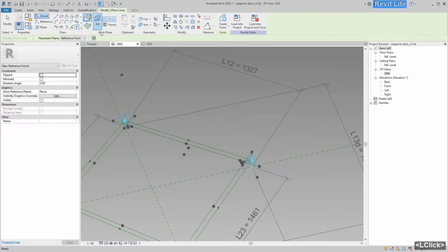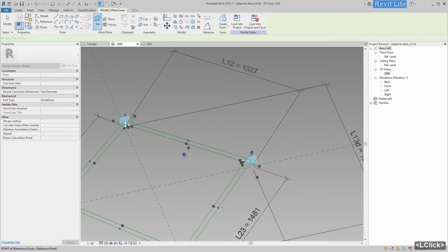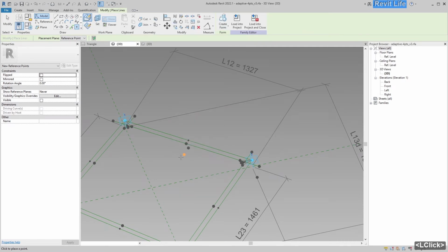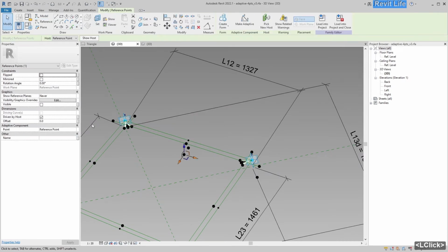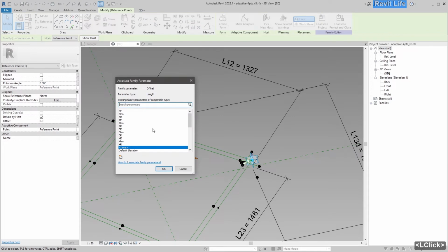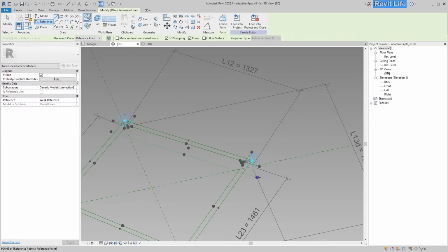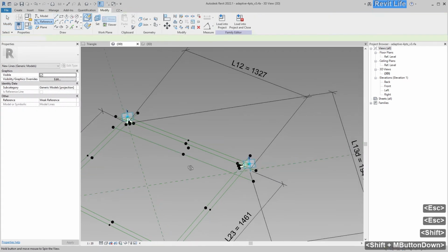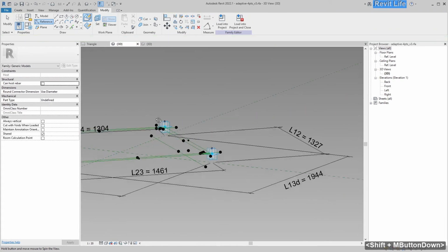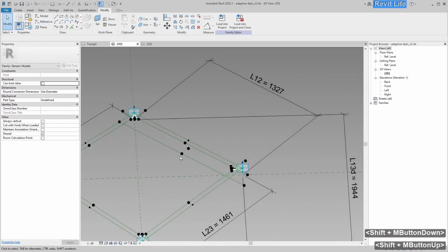Add another point also to the vertical work plane, hit OK, select that point, and we can also reuse the same parameter as above. So this point extends in the opposite direction, also outside of the rhomboid, and we can connect these 2 points and get the offset line for the bottom of this model.